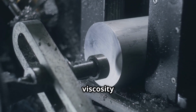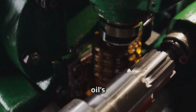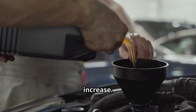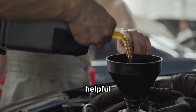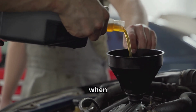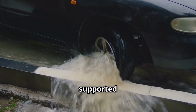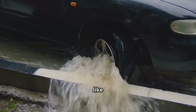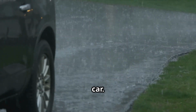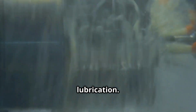If the oil's viscosity is too high, the internal resistance or drag of the oil's molecules will reduce operating efficiency and temperatures will increase. It may be helpful to think of hydrodynamic lubrication as being like hydroplaning when a car tire loses contact with the road. The heavy car can be supported on a low viscosity fluid like water, and loses contact with the road due to the speed of the car. Many of the same factors are taking place in hydrodynamic lubrication.